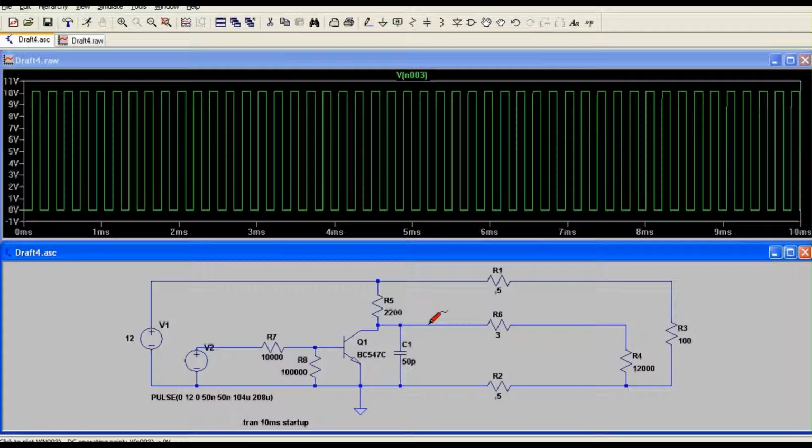This wire here, where the signal is coming through, I'm suggesting that there wasn't as much copper needed to get the signal out to here, so less wire, less resistance. Excuse me, it can have more resistance because the load isn't so much on the end of this. R4, I'm suggesting, is 12K resistance input into some silicon receiver for that signal. I think 12K is not too ridiculous for that.